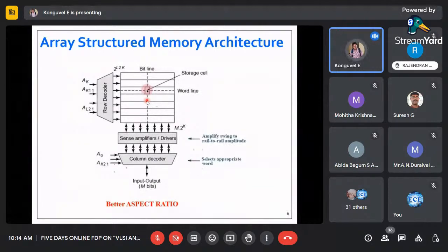But again, we have a problem when we have more bit lines, because as I already said, here we have taken an example of a single word, but that can be a double word also, or a stack of words, more than double also. During that time, the same problem will occur, because we must have that many column decoder select lines.